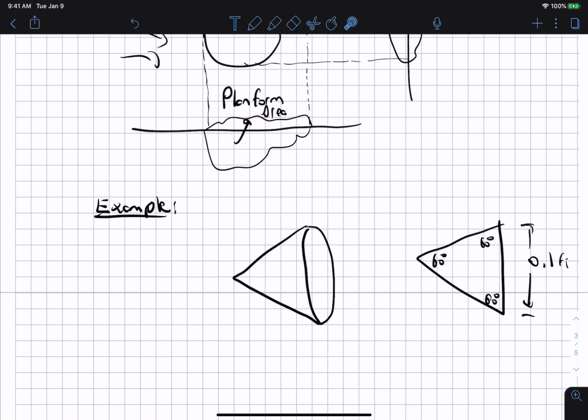And the pressure distribution looks something like this. It is linearly dependent, and the peak value here is 1/2 rho u squared, so it's just the dynamic pressure. On the rear surface, we have a negative pressure, so that's actually pulling backwards. Instead of pushing, it's pulling.